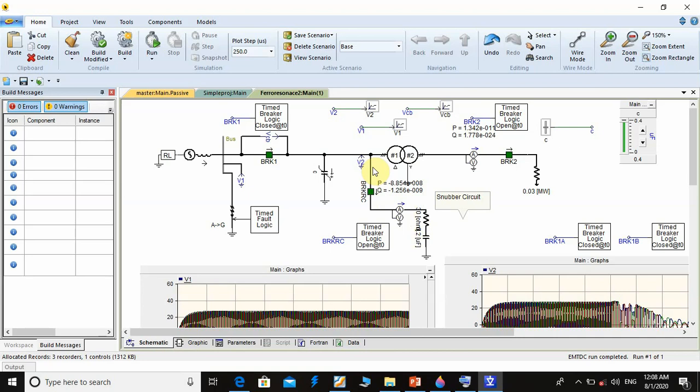This RC circuit works to avoid this overvoltage. When we get overvoltage, the snubber circuit conducts or draws more current, and then we prevent the transformer from overvoltage. The principle looks like a serial resistor, but maybe a serial resistor does not work for this overvoltage.